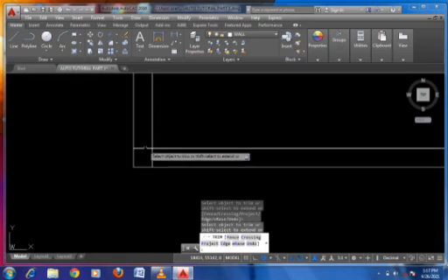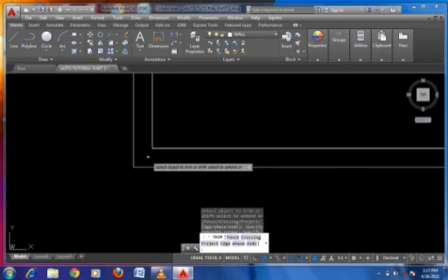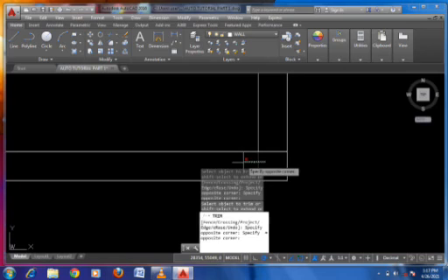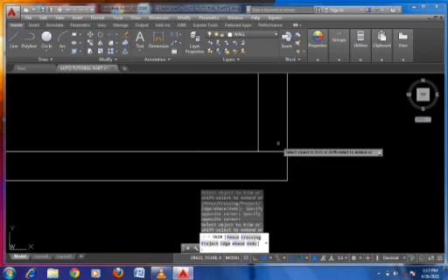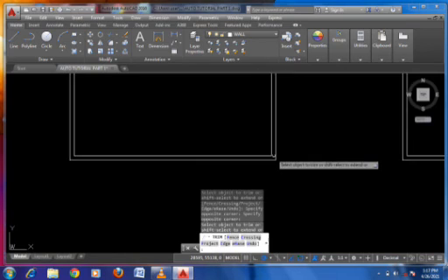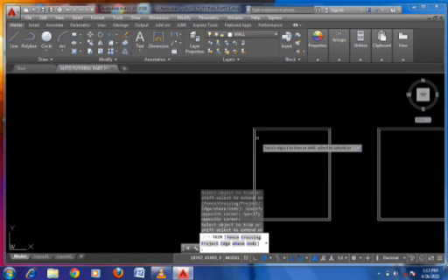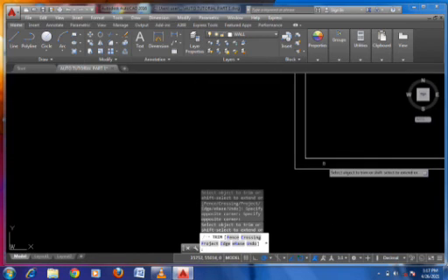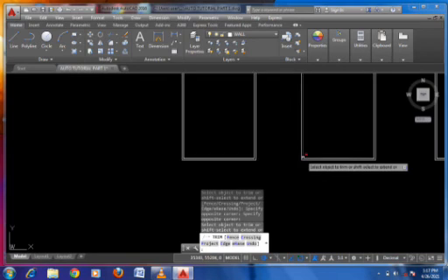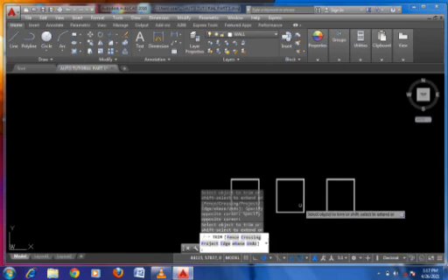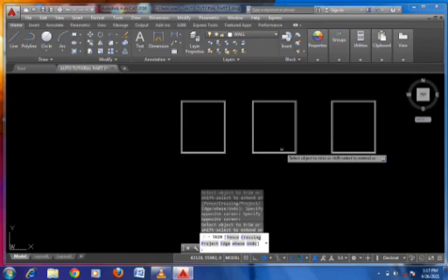You can see that I just zoom in, trim that side, trim that side. You can also trim by clicking outside here and just dragging it to trim it, or you click on that point exactly. So I've trimmed those 4 points. There's nothing to trim there. This place there's nothing to trim because the lines are in one entity, so it was offset perfectly.